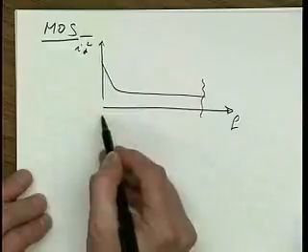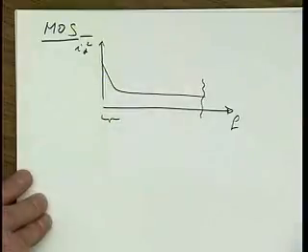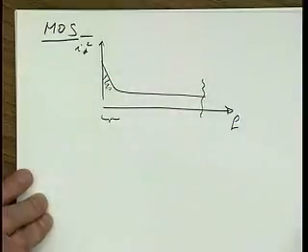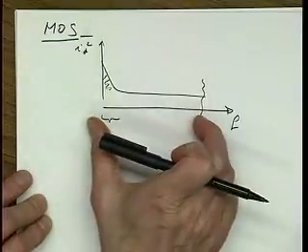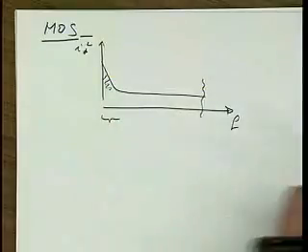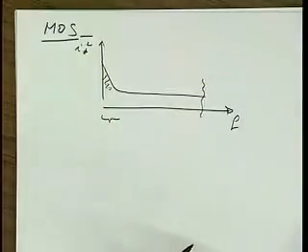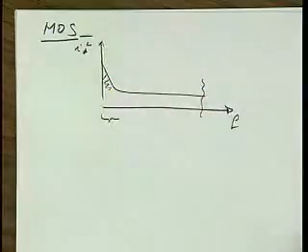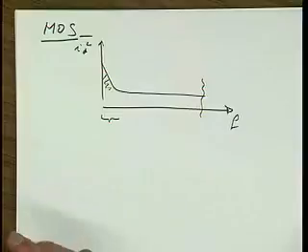And flicker noise is somehow down here, in a 1 megahertz or less bandwidth. This little sliver here may just plain not matter, right? In fact, if I had drawn it to scale, you wouldn't see it, and you would say, well, of course it doesn't matter, right? So that's one thing. The flicker noise may just, or it may be just that our signal is up here, and this thing is going to be filtered away anyways, right? And so flicker noise doesn't matter.